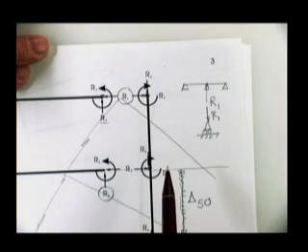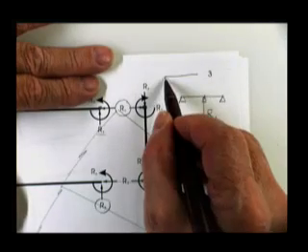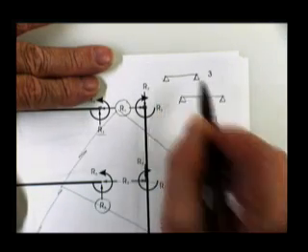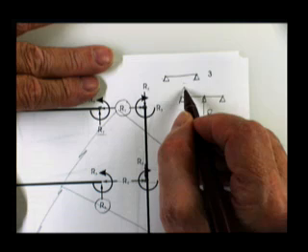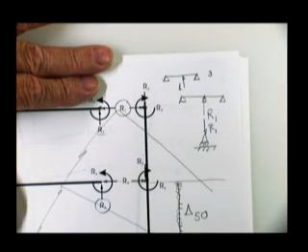It doesn't look the same, I understand, because here's what you saw when you put the unit load on there. You saw a 1. Like in terms of procedure, we first use the unit load to find the delta of the released structure for the real loads.